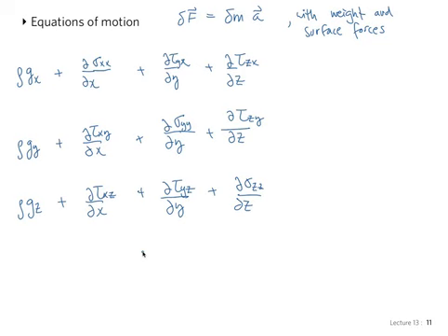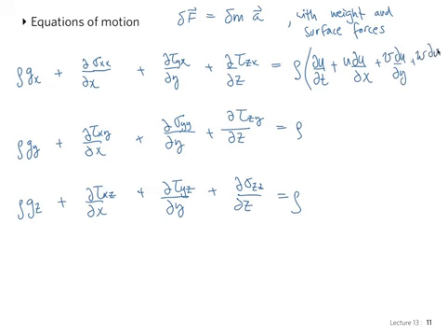We only did the x direction, but we saw a pattern, and we were able to generalize for the other components. And this in every case is equal to mass times acceleration. I've divided over by the volume everywhere, and so I only have rho times the acceleration. The first component, du/dt, plus just nabla applied to u: u du/dx, v du/dy, and w du/dz.